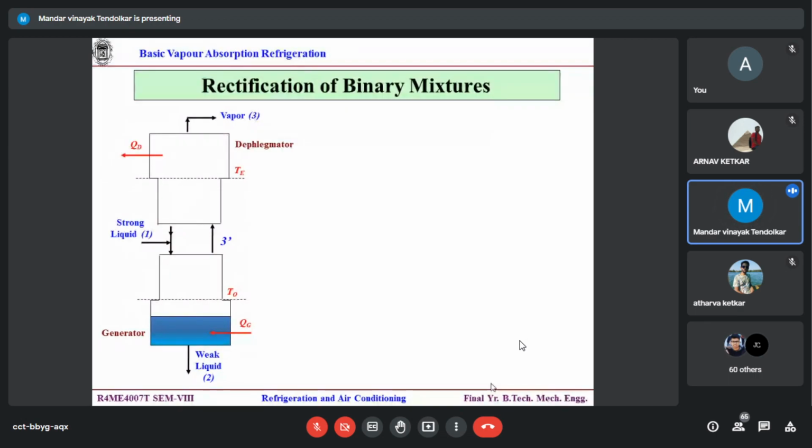But now, let's say 10 ml liquid comes in, you add QG, a little heat, and the separation starts. Now the next lot of 10 ml, which is coming as the strong liquid at somewhere the middle section, is at room temperature. Vapor phase is at higher temperature. So there itself heat transfer starts. So for the separation of the next lot of 10 ml strong liquid, the QG requirement is reduced. What I want? Inlet reduced, COP higher.